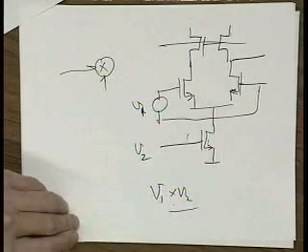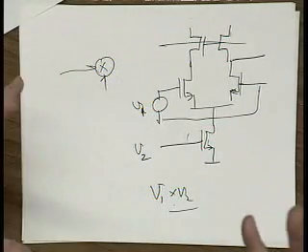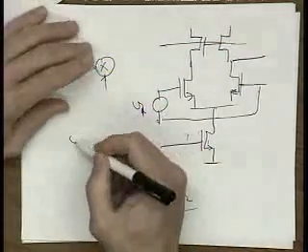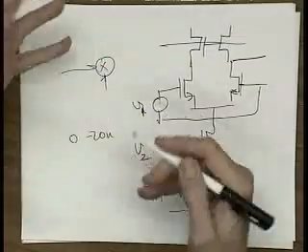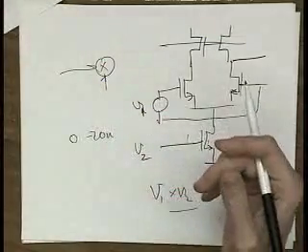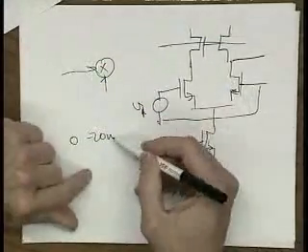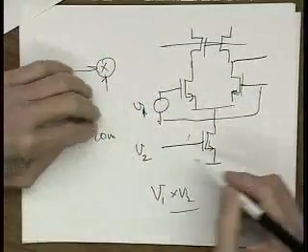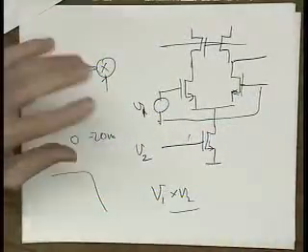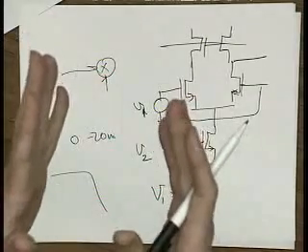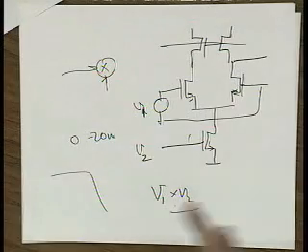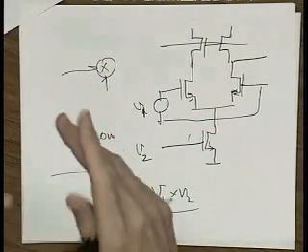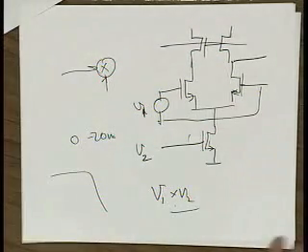And that's what you've been designing all this semester, the baseband circuits. The circuits that work across 0 to 20 megahertz, not at 2 gigahertz, but 0 to 20 megahertz. And there'll be some filters and things like that. I'll show you what a filter looks like in a few minutes. You do a filter so you don't get any of the higher noise. If you've got your cell phone at 2.4 gigahertz, when you mix down, you might have some other noise sources mixed down as well, coming from TV or something like that. Well, you've got to filter that stuff out. We'll do that at the baseband circuits that you're doing.